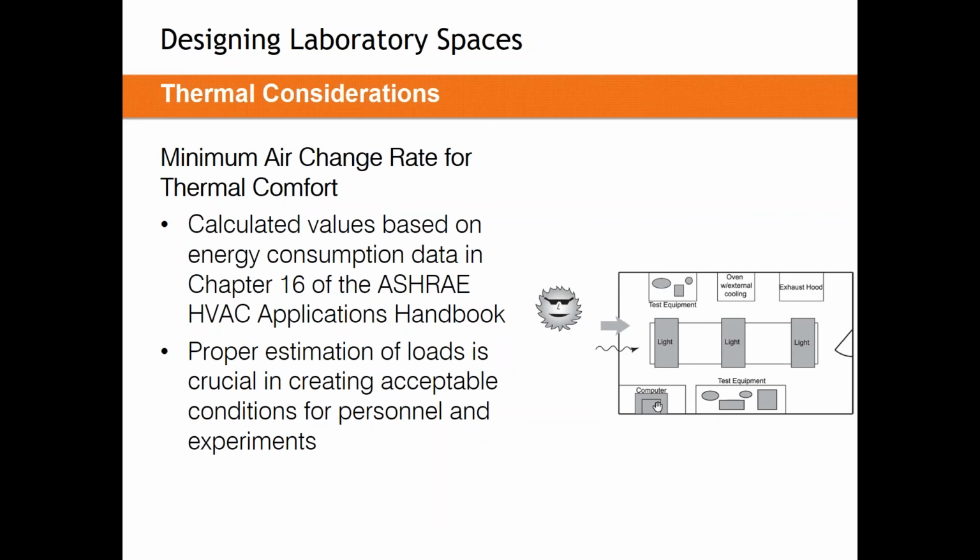So you might encounter a laboratory that is actually driven by its thermal load. You might encounter a laboratory as well that's driven by its minimum air change rate. Or you might encounter a lab that's driven by the fume hoods. But very commonly, you'll encounter a lab where that driving factor changes minute by minute and hour by hour. It can go from thermally loaded to driven by ventilation to driven by the fume hoods, and it can change all day, every day.